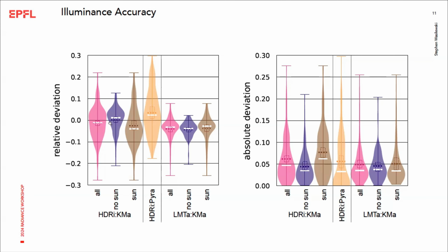And then there's a slight positive bias for the no sun condition, and a slight negative bias for the sun condition, which could be the result of any number of things, because there's aperture correction, shutter speed correction, color shifting, as well as the shadowband merging process, but it seems like it's not that part of it. But overall, the absolute deviations, and again, the HDRs are also not calibrated to this illuminance meter. They were calibrated against a different device. So these are all completely independent.